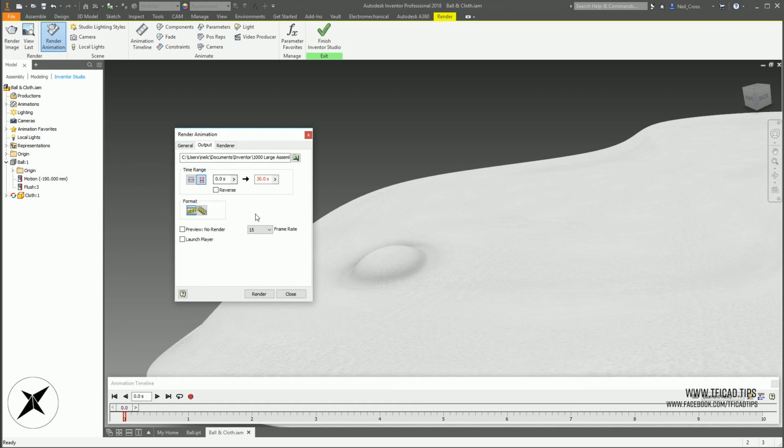Yes, to that. We're going to render 10 seconds because that's pretty much all there is. You can select this here, just the entire animation. It'll detect that it's a 10-second timeline. But you can pick and choose how much of the 10 seconds to animate. If you just want to animate 5 seconds, you can say just render 0 to 5 seconds.